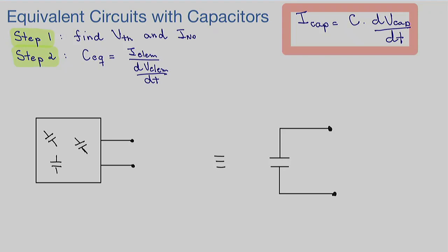Then we measure that device either by applying a voltage or applying a current, which in the case of resistors we called I-test and V-test, right? We measure the IV curve, and then we know how that box is behaving, which means that we can then model it using the Thevenin equivalent circuit or the Norton equivalent.